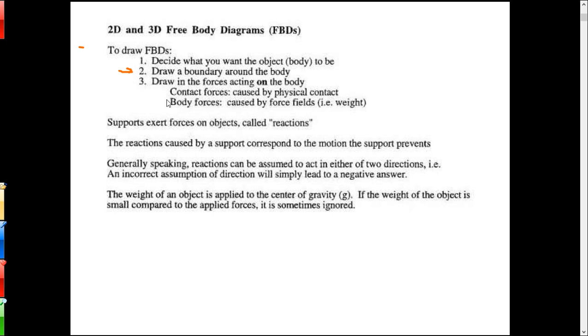And then you want to draw in the forces acting on the object. There's two kinds. Contact forces are caused by physical contact. That's why you like to draw the boundary, because it helps you identify where the contact forces are. Body forces are caused by force fields, which for us is gravity. So weight is a body force. We don't really have any other body forces other than weight. In a class like physics, you might have electromagnetic or magnetic fields or things like that, but we won't deal with that.